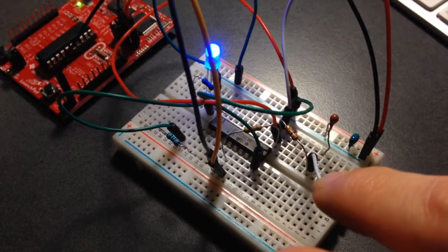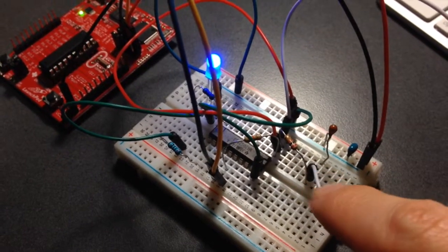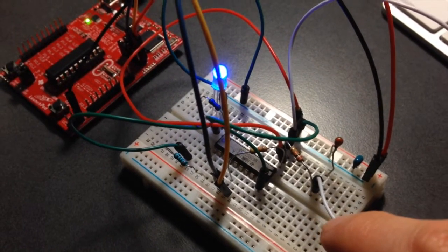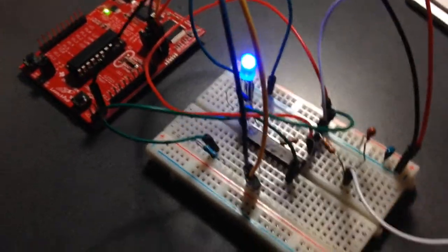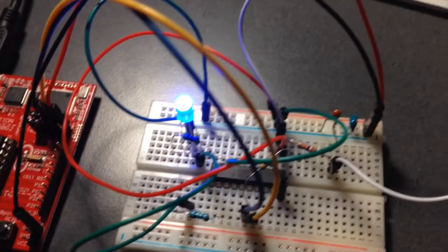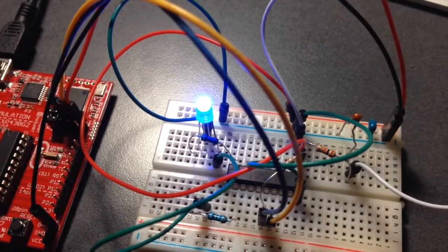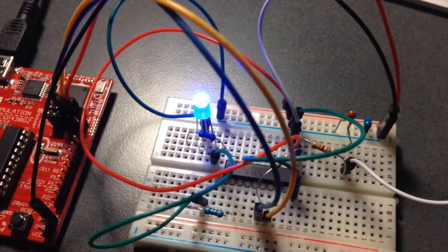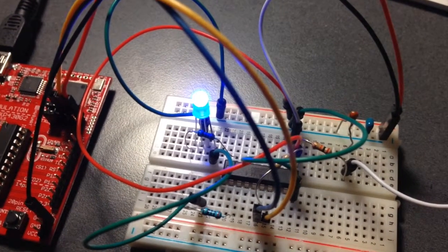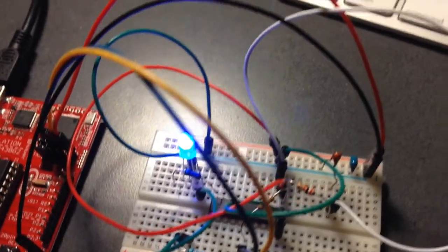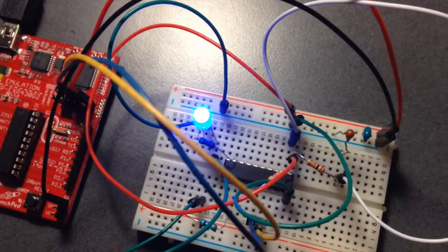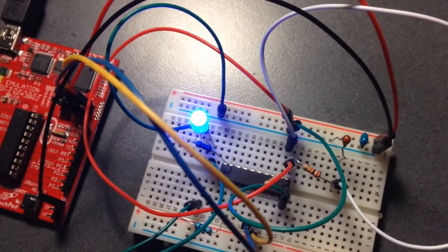So what happens is that the ADC reads the value at this point, this voltage, which is usually in the range between 1 and 1.3 volts. And then this multicolored LED, which we are controlling on two channels right now, the red channel and the blue channel, is adjusted using pulse width modulation to give the effect of dimming one color versus not dimming another, and we can regulate the color between all red, all blue, or a purplish gradient in between.